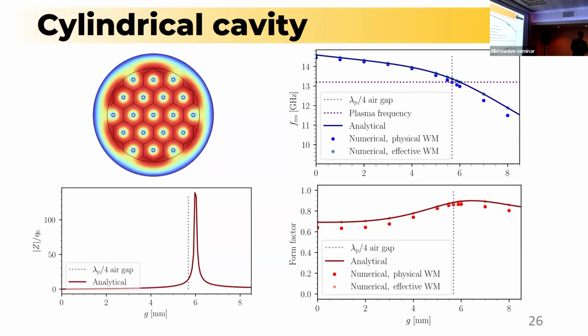There are some challenges here. Previously, in the square cross-section cavity, the unit cell was also square, so everything fits perfectly to have an exact number of cells inside the cavity. This time, as our cross-section is circular, it's a bit challenging to define exactly where we are going to stop our wire media, exactly where we are going to define this first boundary, right?